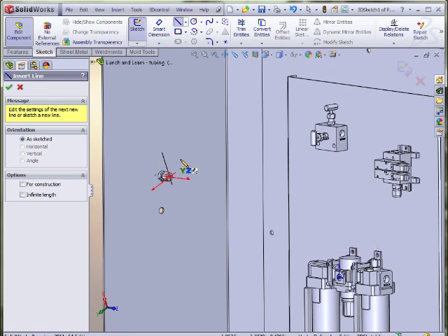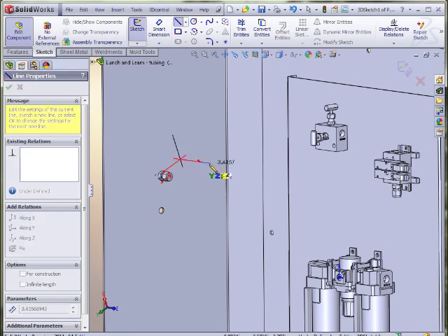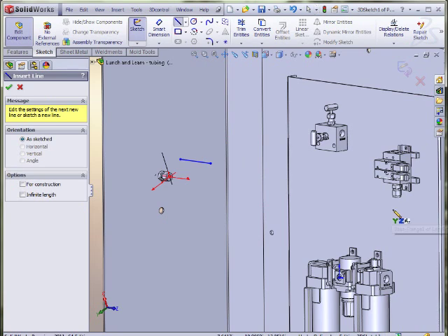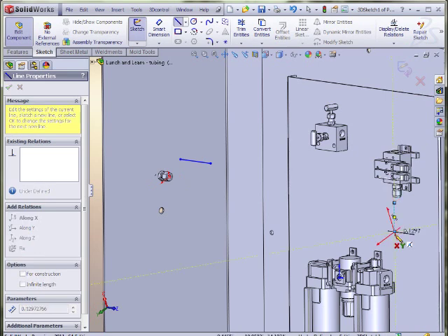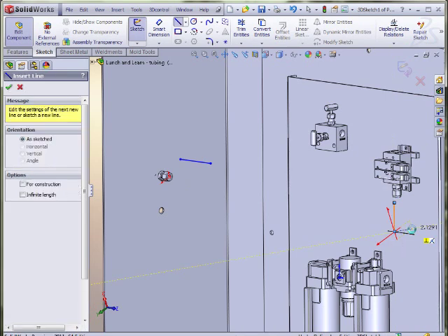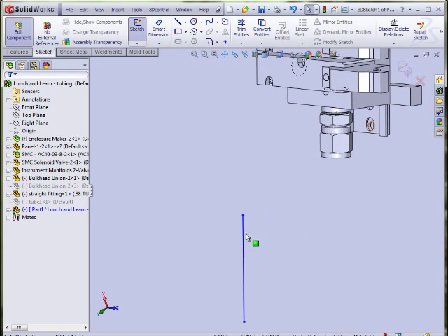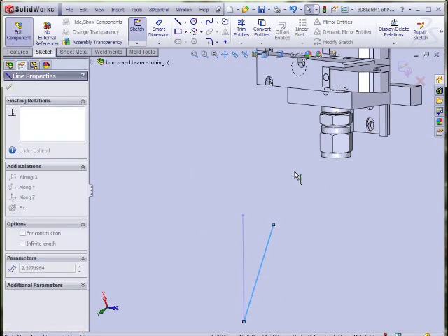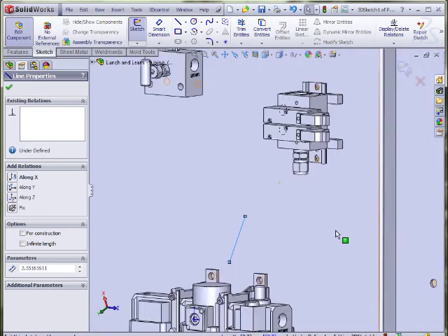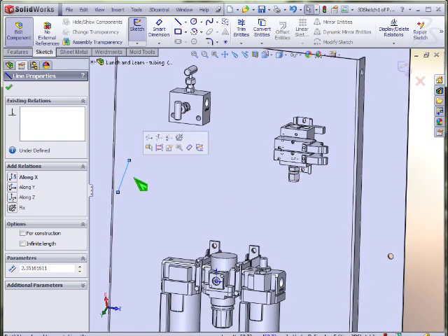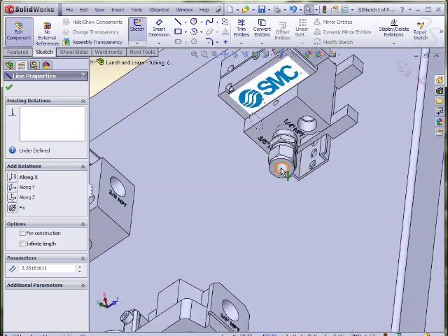There's a couple different ways you could probably tackle this. I'm going to create a couple of short line segments and then put a spline between them. You could draw lines like I did in the previous example, all connected end to end, and then possibly put your sketch fillets in there. But just to mix things up a little bit and show you a different example, we'll do it a somewhat different way. When you're working in a 3D sketch like this, sometimes things can appear to be in a position that they're really not, so that's the case with this line here. But as I've mentioned in the past, make the geometric relations work for you. It doesn't matter if this thing is necessarily off in space a little farther than where we wanted it to be. We could try moving it, or we could just add the relationships.